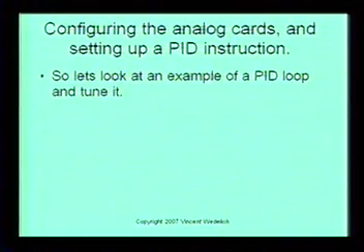Actually, I think one of the courses I keep getting pestered to do is the variable frequency class. With a VFD controlling a fan and a damper, allowing the fan to push the damper open and close, you can tie the damper to a rheostat, a variable resistor, and bring that into the input of your PLC, convert that variable resistor value into a 4 to 20 milliamp signal, and control the fan speed so that you control the damper and the airflow. That's what I've been asked to do, and I honestly just haven't had a chance yet.